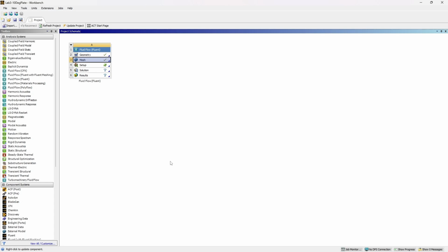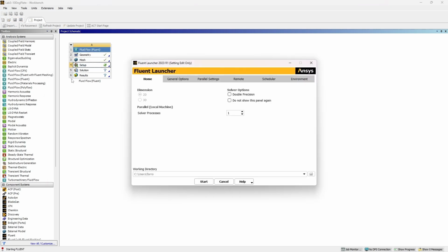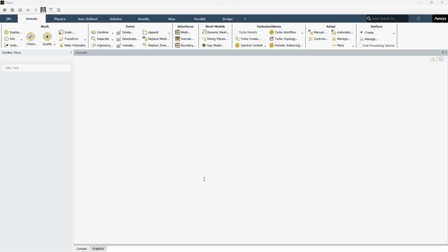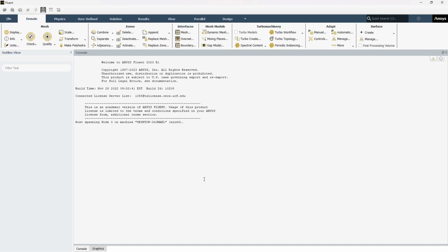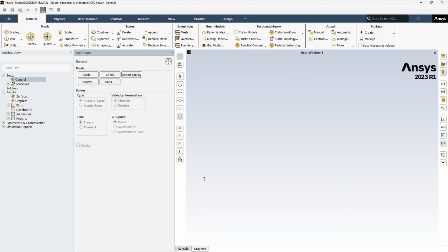We're going to change the local processes from 1 to 8. You'll see this UI in a second. So once this occurs, this will help speed up the simulation. It'll just use more of your local machine's cores in your computer. So here we go, 1 to 8. And of course, double precision for more accuracy, less truncation error and stuff like that.